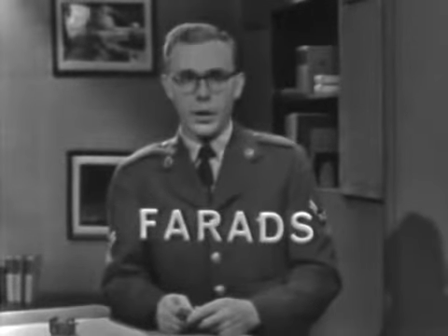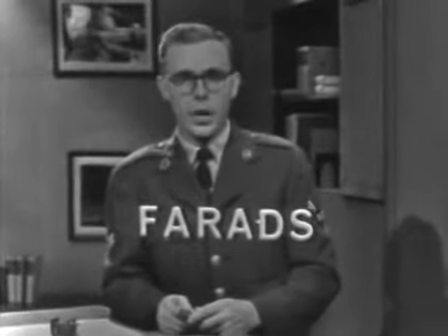In the capacitor, the energy is stored in the electrostatic field. The ability of a capacitor to store electrons when charged is measured in farads. A 1 farad capacitor connected to a 1-volt battery would have 1 coulomb of electrons on its negative plate. A 1 farad capacitor would be a gigantically large capacitor.